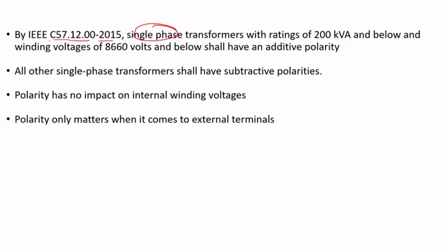polarity only applies when you're talking either single phase or one phase of a three-phase transformer. So you're talking about one phase at a time. Three phase, we talk about phase angle displacement. It's a separate thing. But when you have single phase transformers that are rated 200 kVA